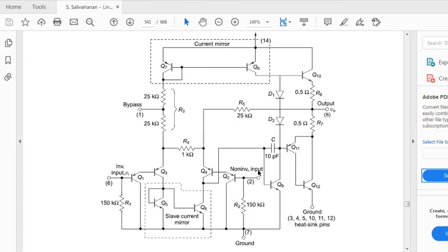So this is the arrangement of your audio power amplifier. So if you have seen, here you are having the first stage, which is formed by this Q1 and the Q2. Okay, which is then a PNP emitter follower input stage. So its output drives your Q3 to Q4 combination. Okay, so this is a differential pair arrangement. So one of your Q1, it accepts the inverting input, and another one accepts the non-inverting input. Okay,